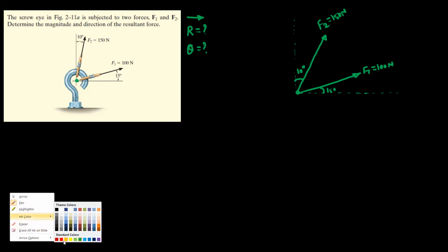As per the law of triangle, we need to represent these forces as sides of the triangle. So for the triangle, select one point. Show this first vector as one side of the triangle. So this is the first side of the triangle. This vector is drawn exactly parallel to this vector, so this vector is nothing but F1. I will take this as A, so the vector AB is nothing but the force F1.